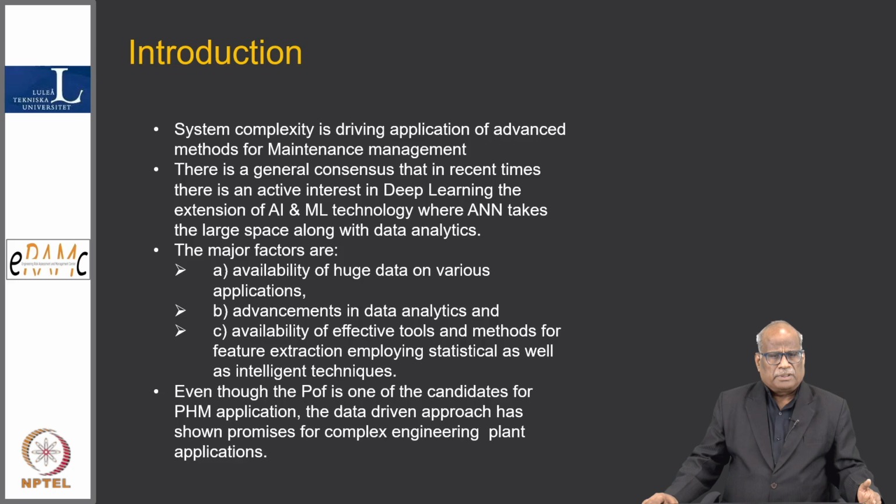So a domain person is not sure what he will do about the probability, though probability is useful in identification, prioritization and all that, but he doesn't know what high and low mean in the control room of a plant. So what he says is, if you give me the instant of failure, or when it's going to fail, that is the remaining useful life, it is useful to me. And that is exactly prognostics and health management. It is one of the major goals.